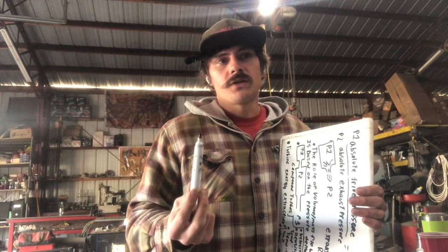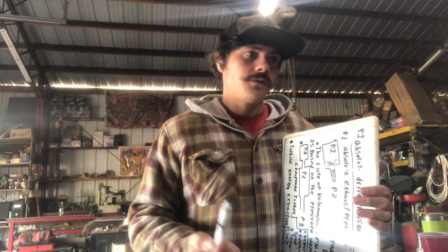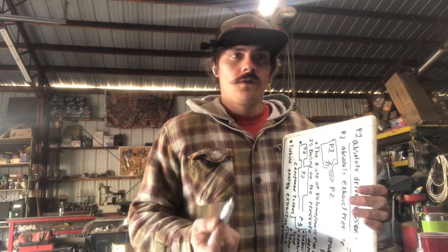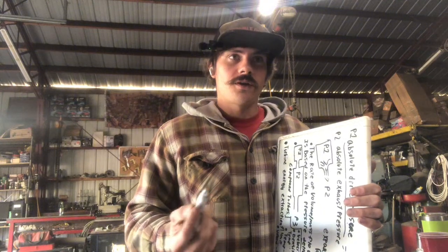Right, that's pretty cool. Given the motor has to be designed to operate at the higher drive pressure conditions, this motor is designed to operate with the VGT turbocharger. So cam, head, all that stuff, right? It's all designed around the fact that you're going to have high drive pressure, and as long as the design of the motor is made for that, then you're in good shape. Most of your factory diesel motors are all designed for high drive pressures.